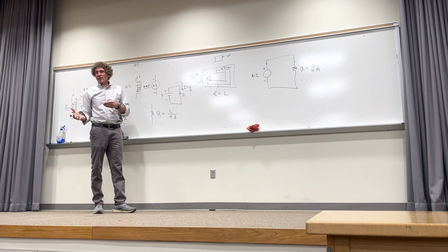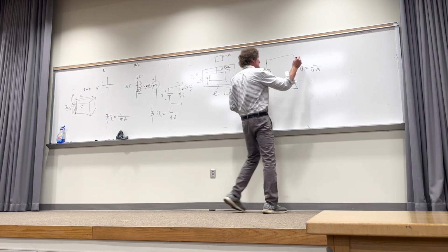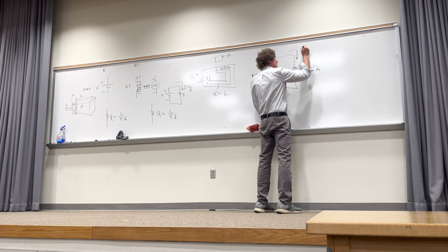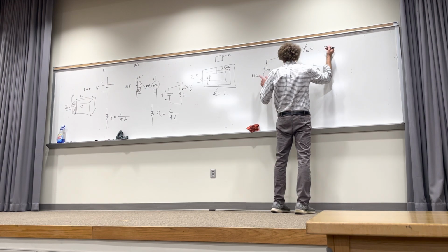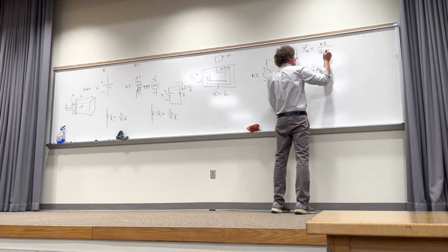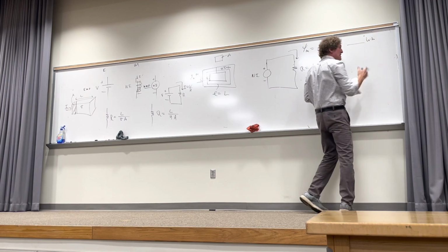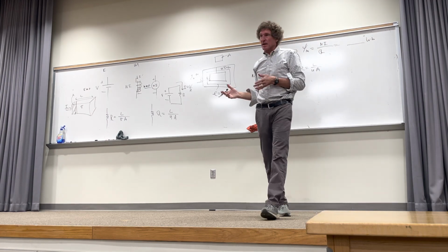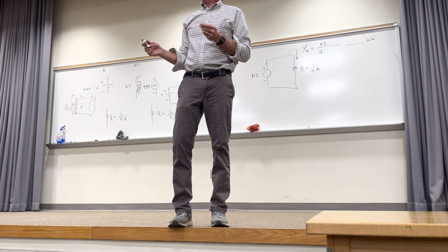All right, well, the equivalent to magnetic current is called flux. So when we take a look here, the magnetic flux, which is in Webers, is simply equal to the magnetic voltage, Ni, divided by the total reluctance. And the units of this are Webers, but it's like electric current. The parallel is exact, by the way. All right, y'all with me so far?